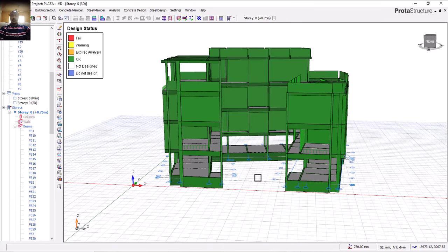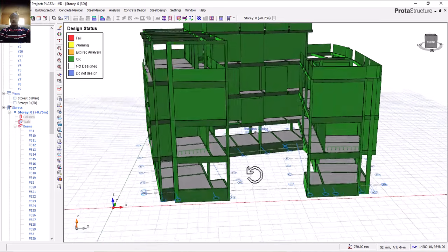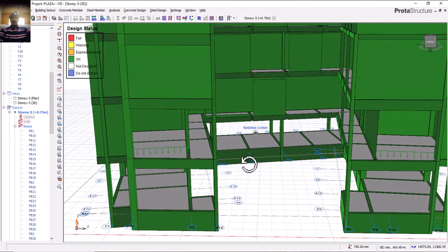We have tried to use a patch, and you can see how it was failing. Which we are now explaining that we have to go for beam raft. You can even see that we are using a beam depth of 1,400, and yet we are discovering that some reinforcement needs adjustment.